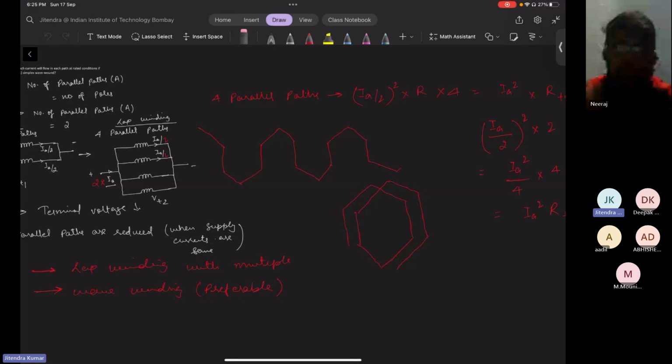That's why sparking happens, and proper positioning is not possible. We cannot maintain the armature at a certain position for a long time, so a spark occurs. In some scenarios the winding can be burnt or the temperature may rise, and on top of that, circulating current also flows in the winding. That will be disastrous, right? So there has to be a solution, and that solution is the equalizer.